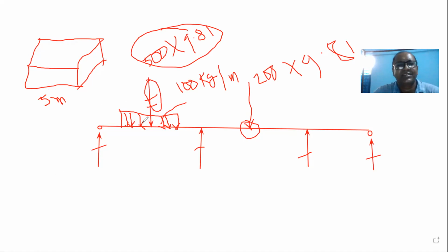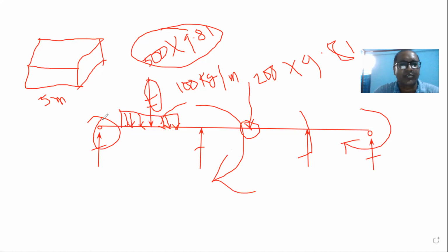But say you have a shaft, and you are applying torque over here. This torque will be all the way distributed coming to this end. Unless you fix somewhere or you apply torque again at the middle, all the torque comes to the other end. But if you fix it at some point, then you need to figure out the reaction torque. Okay?